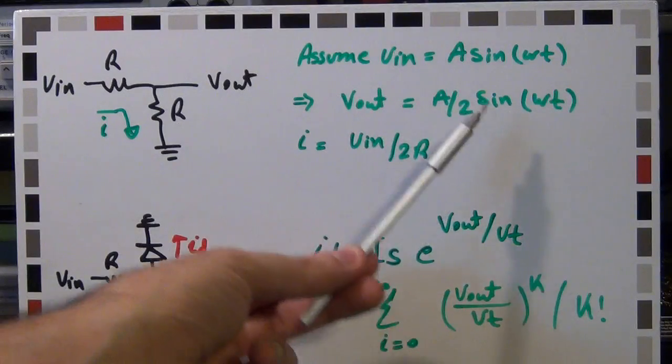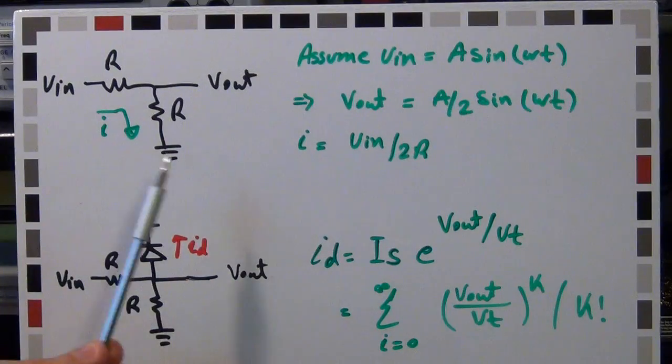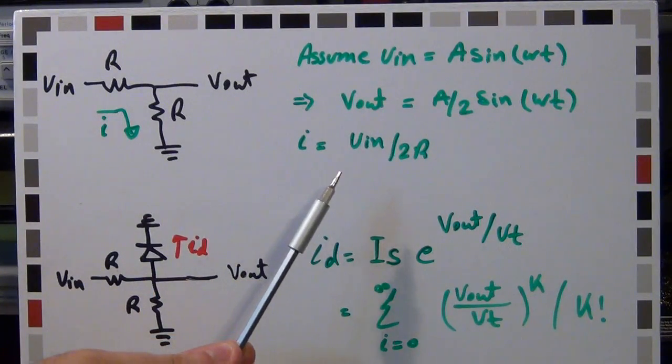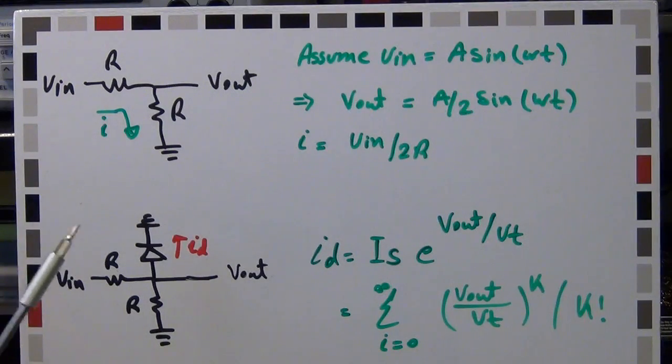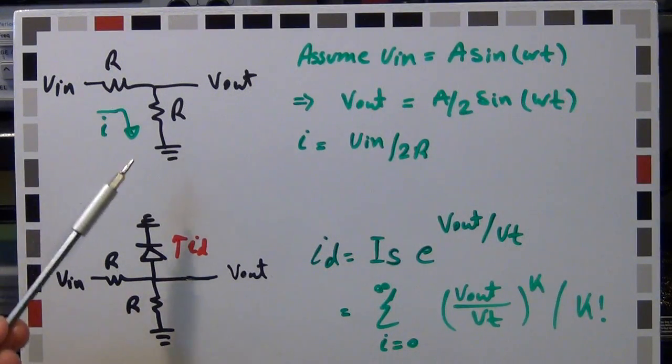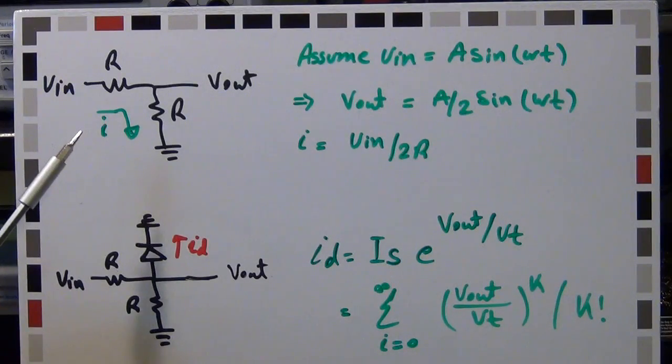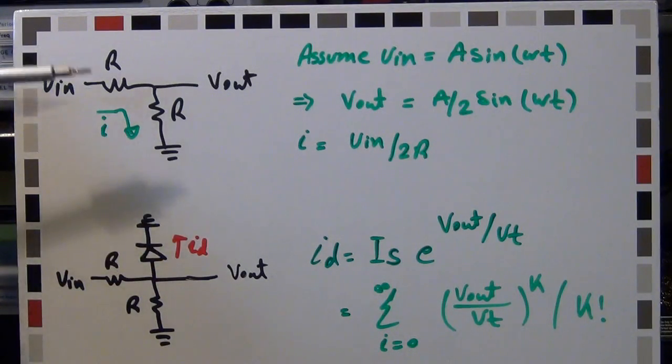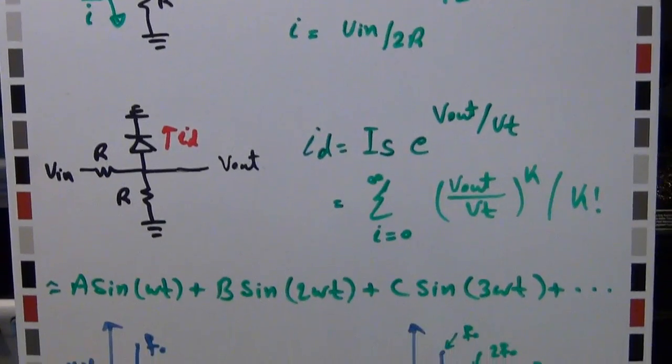And the reason why this is a one-to-one linear relationship is because the current versus voltage relationship of a resistor is linear. It's Ohm's law. So the current times the resistance is the voltage, which is a linear equation. But this is not always the case, because although resistors are linear, many other circuit elements such as transistors and diodes and so on are not linear circuit elements, and they can add nonlinearity. So let's look at the most simple case of building a nonlinear circuit so that we can actually build it in the lab and start measuring.